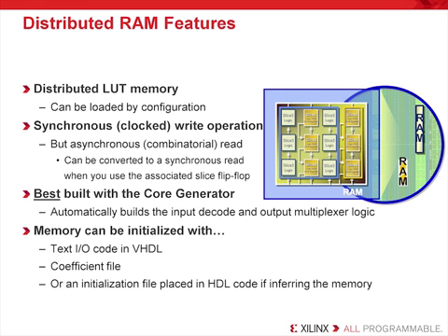As I mentioned, distributed RAM can be initialized during configuration so your FPGA can start with your memories preloaded. The write operation of distributed RAM is synchronous and the read operation is asynchronous. The RAM output can be connected to the flip-flops in the same slice to create a synchronous read.